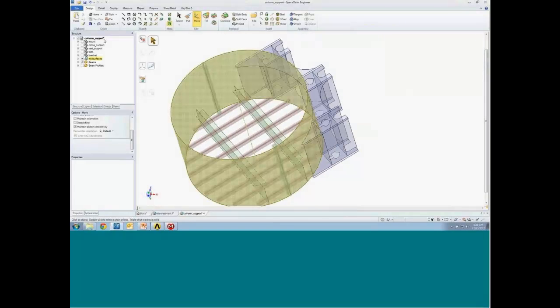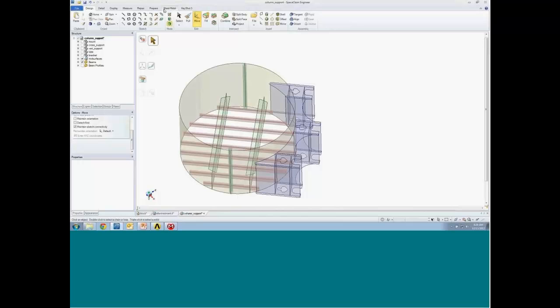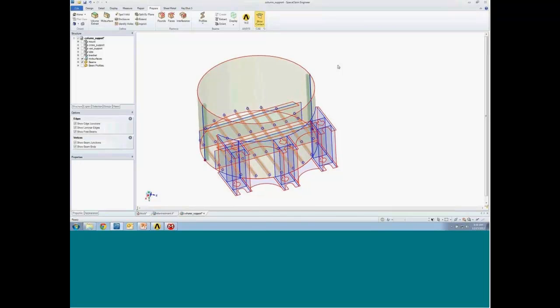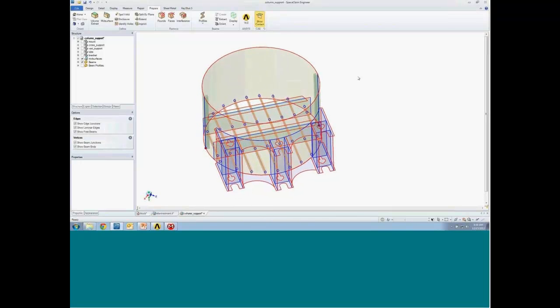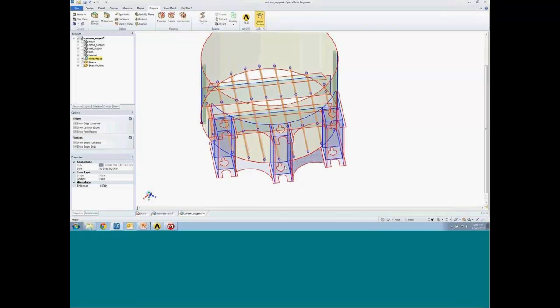One more thing I wanted to show that I forgot about. I want to turn on an option called Shared Topology, and this is part of the integration between SCDM and Workbench. What this does is if I want to see where all the edge-to-face connections and edge-to-edge connections are, I can click a button called Show Contact. So everything in blue is where I do have a connection point. Everything in red is a solo edge or point. There's a couple of faces, namely 4 of them, that do not actually touch other edges.